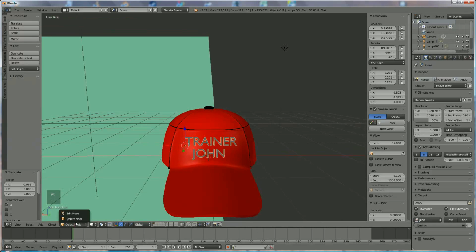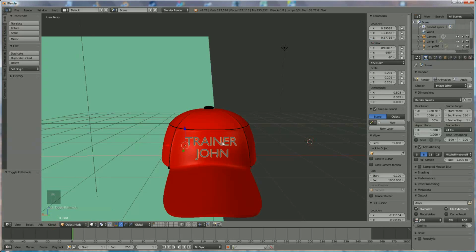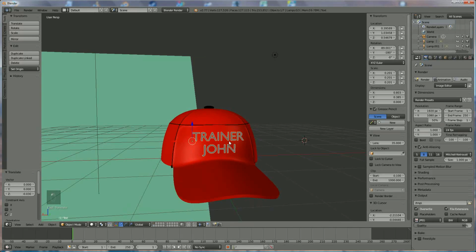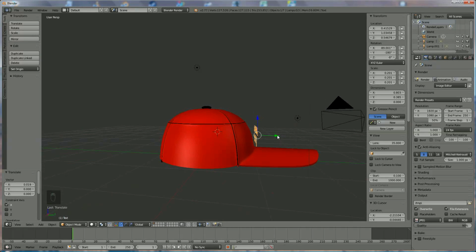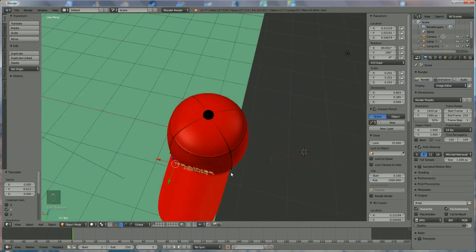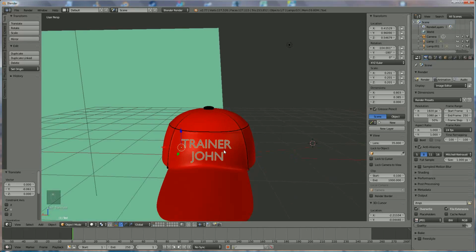Now, if the text is not looking so good like you want, for instance, I want mine to be more to the center like that, it's no problem, you can do that always. If your text is looking okay and it's positioned where you want it to be, like this, in the front, also okay. Now we rotate a little bit so it is angled to that one, and we do that with the RX command, let's say 15 degrees. Yeah, 15 degrees will be like it. Press enter, move it a little bit aside, but still so that you see your text.